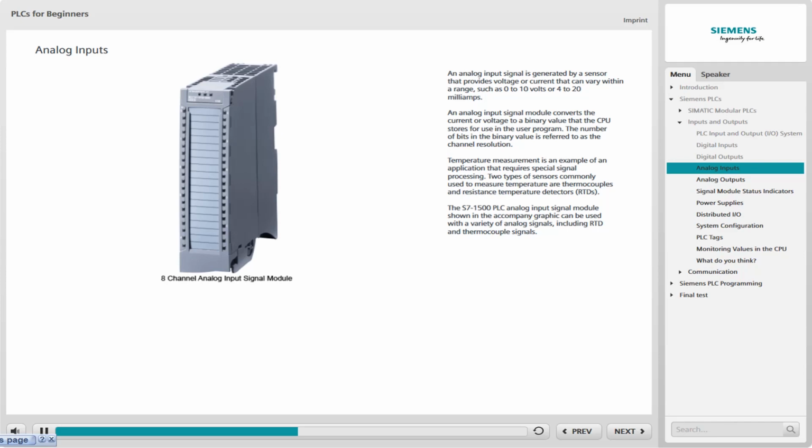A thermocouple is a temperature sensor made from two dissimilar metals joined at a point called a junction. A thermocouple produces a small voltage that is temperature dependent. An RTD, also called a resistance thermometer, is a temperature sensor made from a metal such as platinum, nickel, or copper that varies in resistance in a predictable manner as temperature varies. There are various types of thermocouples and RTDs, and each type has different characteristics that determine its application range.